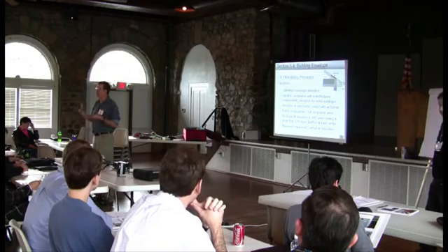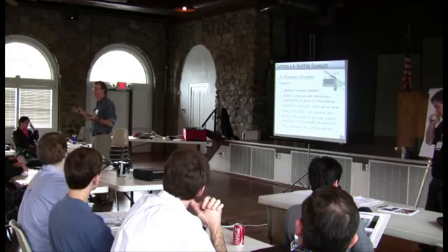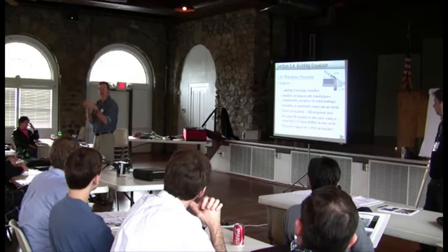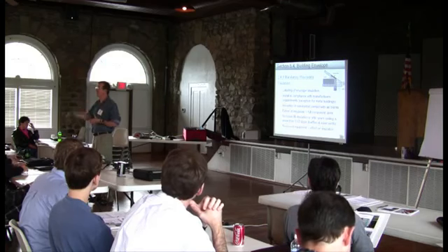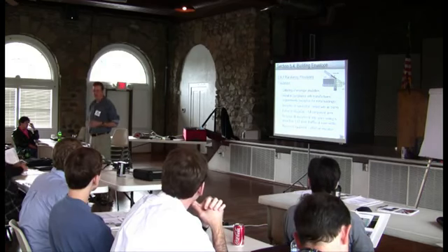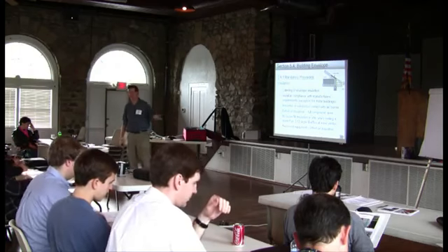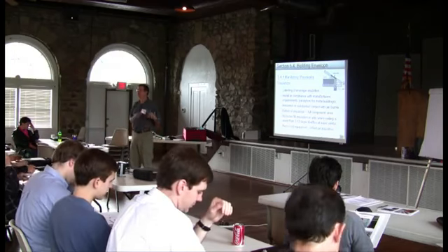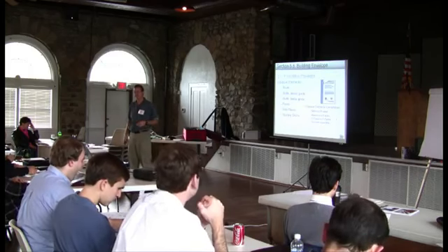So for example, if you have a recessed light fixture, they want you, like we saw yesterday, to use the airtight IC-rated recessed light fixtures, the ones that are both airtight and that you can insulate on top of them, insulation contact. Anything else big on this, Brandon? I'm just trying to hit the high points. A lot of these are just the rules you follow if this applies to your project.